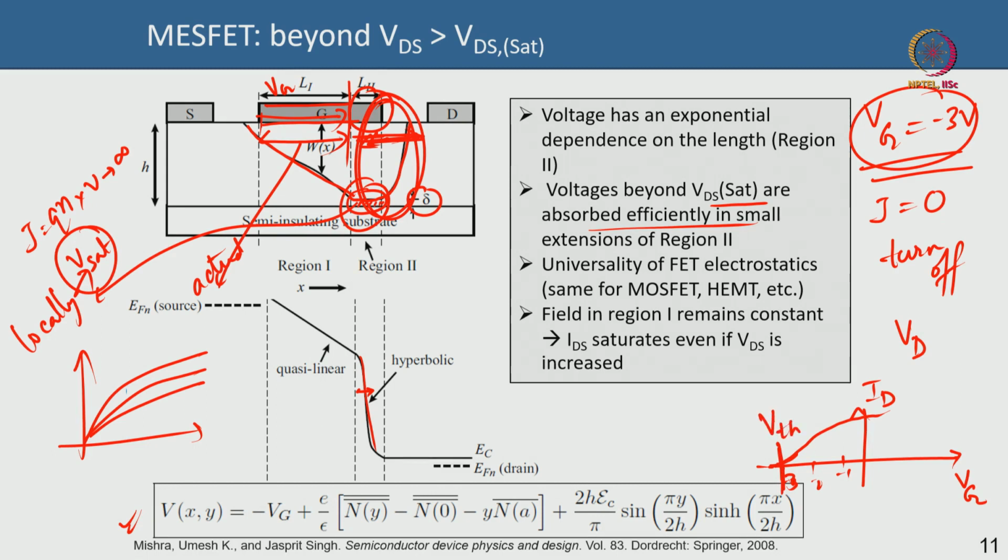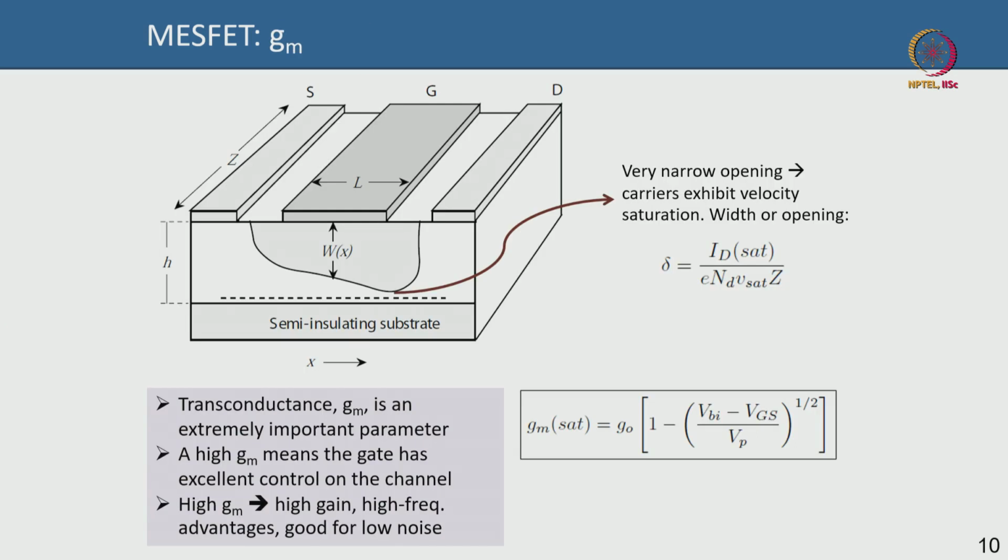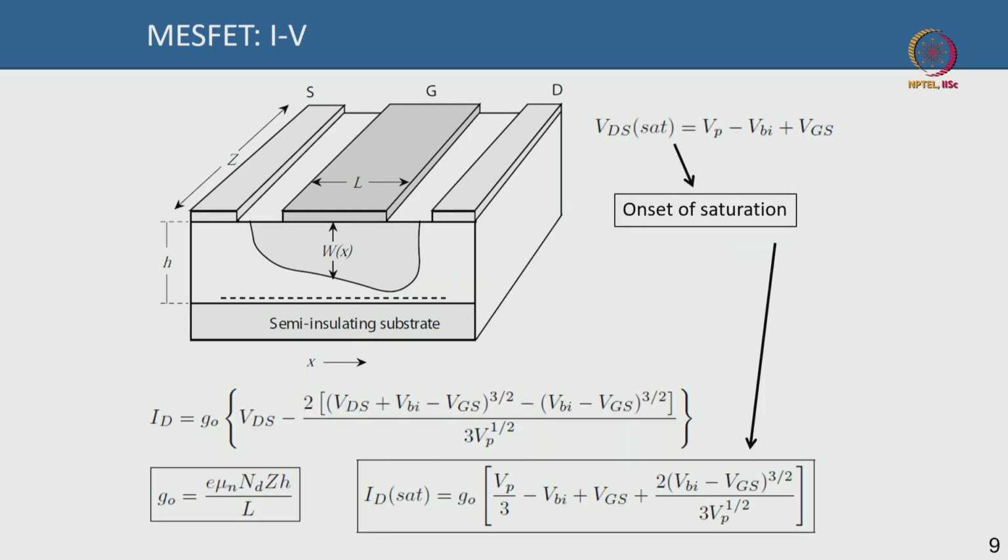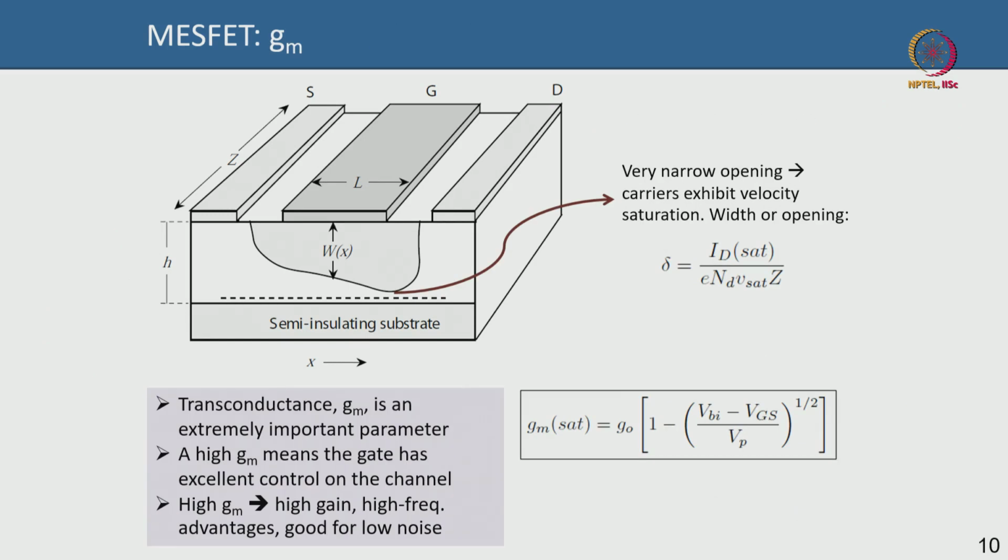Below -3 the channel is off, no matter what your gate-drain bias is, provided it is lower than the 3 terminal breakdown. However, when the gate is not lower than -3, but somewhere in the range from 0 to -3, then the drain voltage can pinch the channel off locally near the drain, but it does not mean the channel has become 0 thickness. I have been repeating this statement because it is the most important part to understand how the current actually saturates in a field effect transistor.